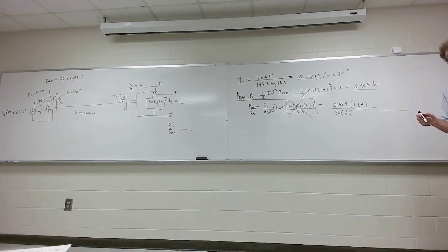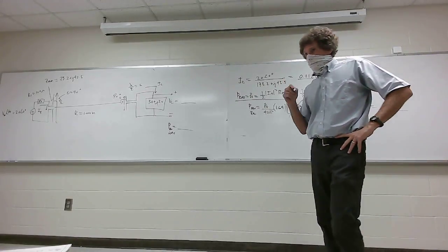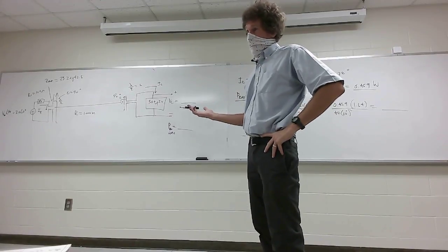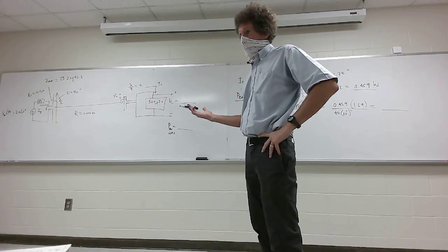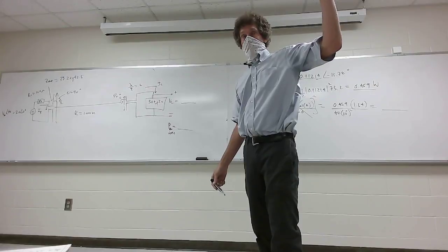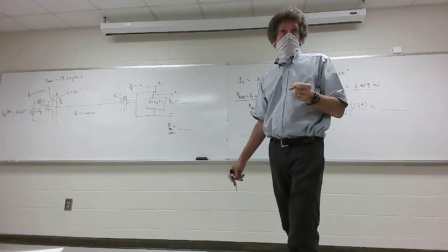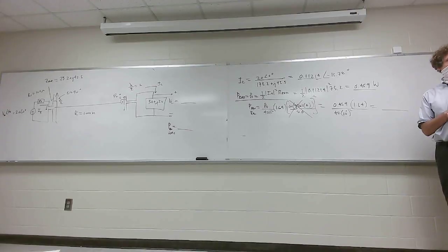Where's 1.64 from? Remember the gain of a half-wave dipole is 1.64? Or the maximum gain, or maximum directivity, do you remember that? And for a short dipole it's 1.5, or 3/2. I remember 1.5. How many remember 1.64? Okay, it is, and you've had several problems on it. I gave that to you on the quiz, but you should get familiar with that one, because it's used so often.